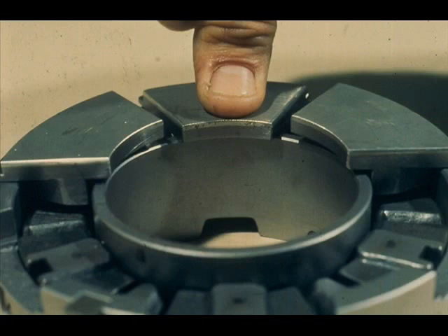Thus, as demonstrated here, a deflection downward of the center shoe because of too much thrust load on it will, because of the leveling pads, cause the adjacent shoes to rise upward to assume more of the thrust load.